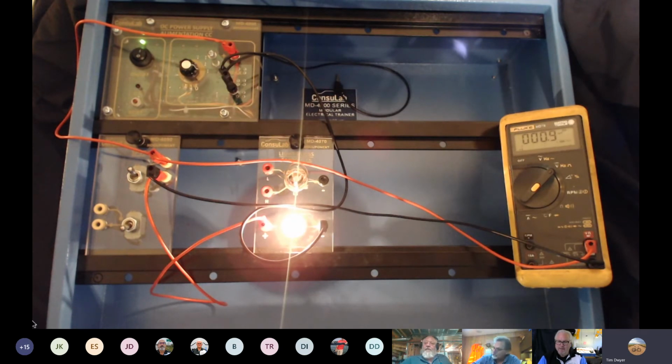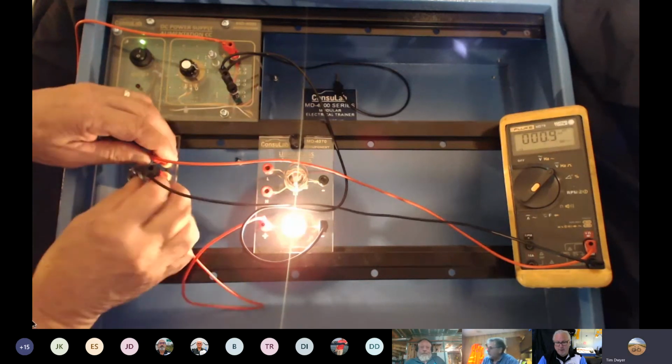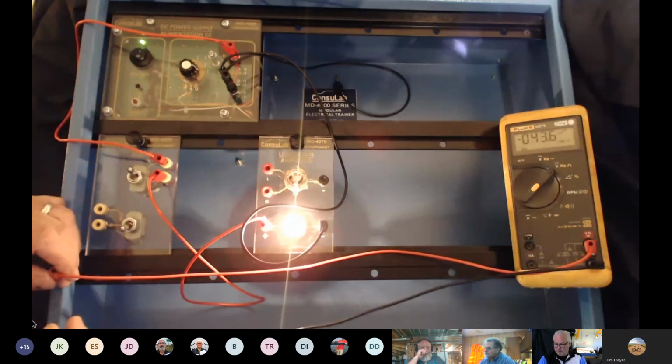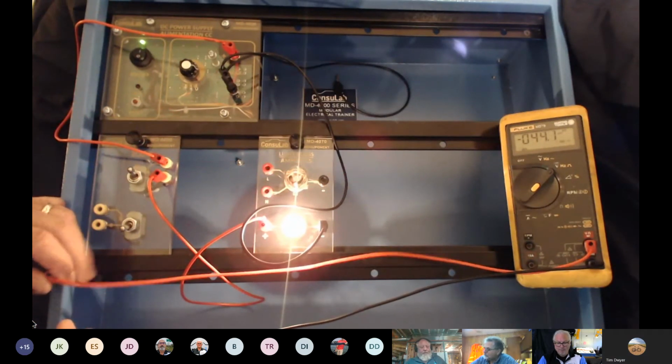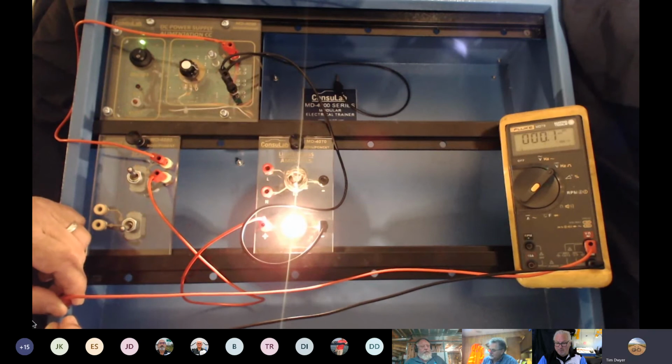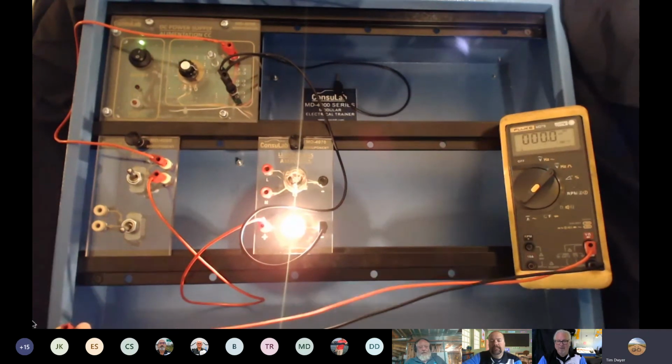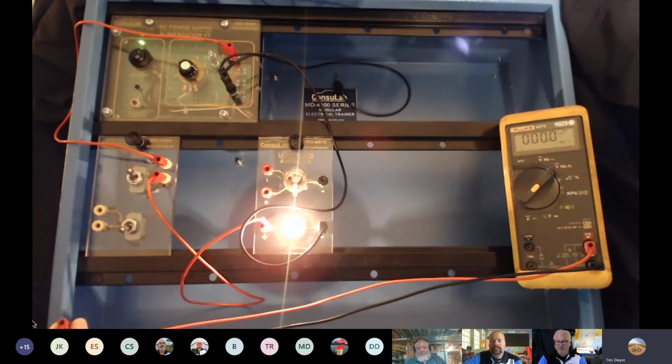So I think that you fix maybe 85 to 95% of your electrical problems right here. It's not more complex. I've seen too many of those open battery cable pressed on ends with corrosion. Oh yeah. That have been ignored.